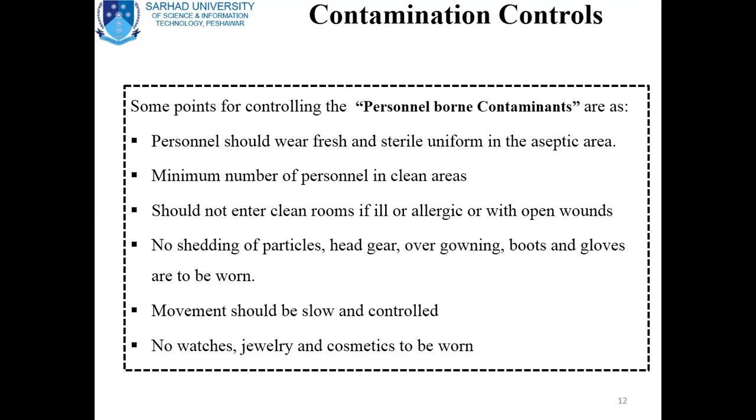If a person is allergic, has flu or any other allergic condition, or has open wounds, he should not be allowed to enter the clean room, in order to avoid personnel borne contaminants entering the product and causing contamination.